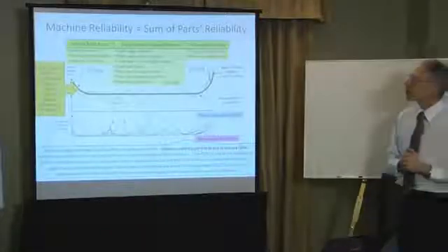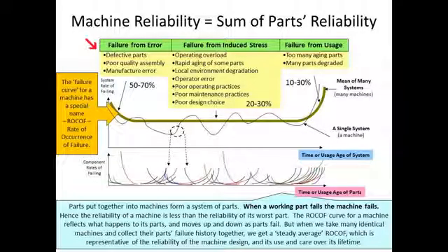We know why machines fail. Things like defective parts, poor assembly, manufacturing errors, operating overload, aging of parts that are aging but not replaced, local environment degradation. This is an example of our lubricant. If our lubricant gets water in it, the local environment degrades. If it gets wear particles or dust and dirt, the oil is degraded. And of course, eventually things do age.